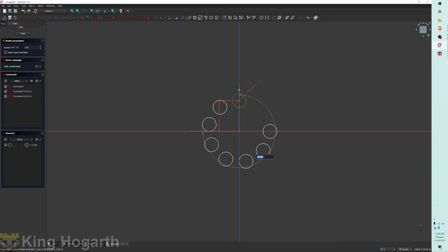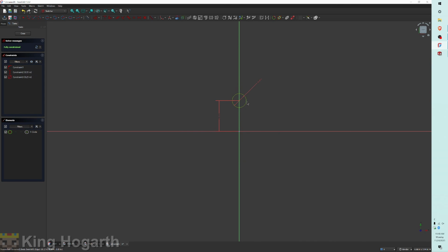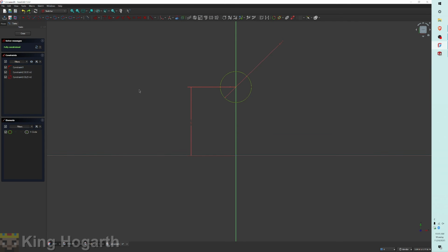Oh my goodness. What's that? 1, 2, 3, 4, 5, 6, 7, 8. Okay. So we do have to put -1, because SolidWorks counts the thing you're copying as 1. We select the circle. That's what we're copying. We click this guy. I forgot to put the number in.